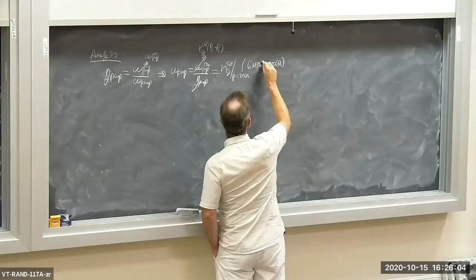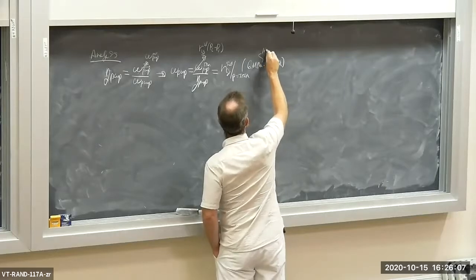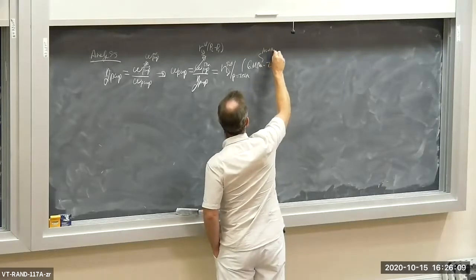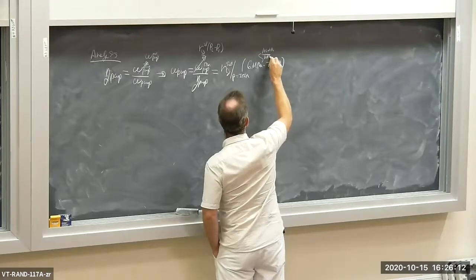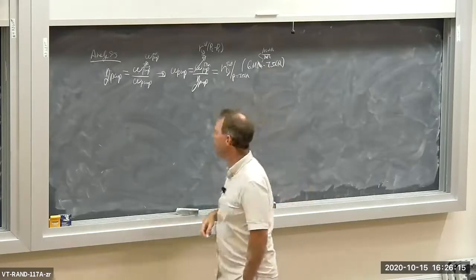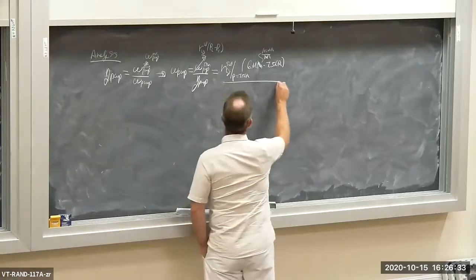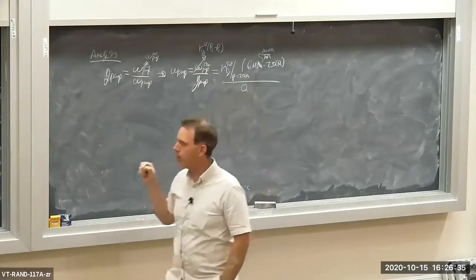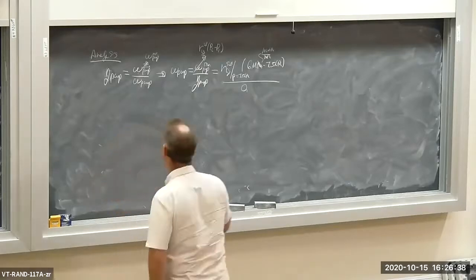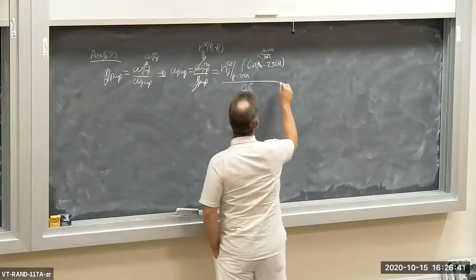Obviously I've got to do a unit change there. There are 1,000 kilopascals per 1 megapascal. So 6,000 minus 7.5 kilopascals. All right, we crank through and we find that the isentropic pump work is 6.04, or 6 kilojoules per kilogram. I'm sorry, what's the isentropic efficiency of the pump? 80%, so 0.8.